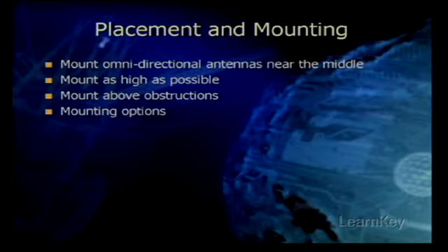Also, with mounting, once you have calculated the necessary output power, the gain, and the distance that you need to transmit your radio frequency signal, and you've chosen the appropriate antenna for the job, you've got to mount it. There are several mounting options that you'll have, whether it's a ceiling mount, a wall mount, pillar, or ground. You need to make sure that you do follow the appropriate procedures. There is no perfect answer for where to mount your particular antenna because everybody's environment is going to be a little bit different.